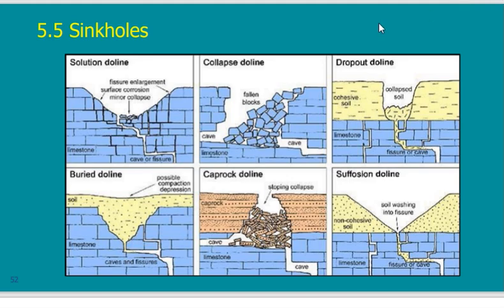Why are we given these different shapes? Because you will be asked to go to a site and to check this site. So what you have to think of is the shape of the surface. If you go to a site and you are on top here, or on top here, or here, or there, or here, how can you expect that this will include sand dunes? This one especially, seeing minor depressions in the soil means that, especially when these depressions are rounded, there is a big possibility that below you have sinkholes.